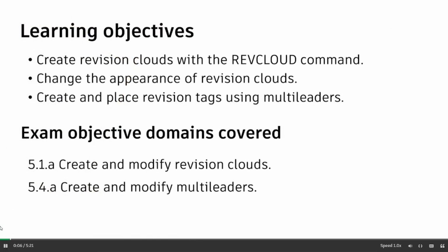I'm going to be reviewing different markup tools available inside of AutoCAD. I'm going to be marking up a drawing using the REVCLOUD command. And I'm going to use the multileader tool to add a revision tag to the REVCLOUD.